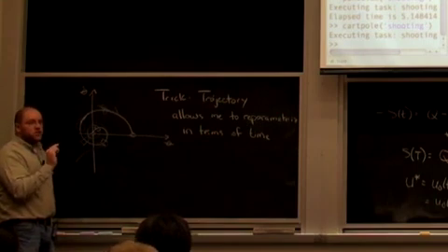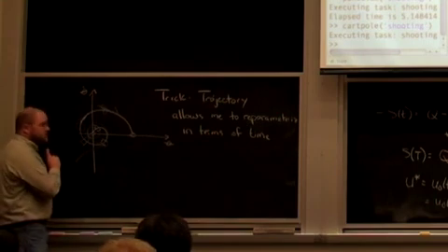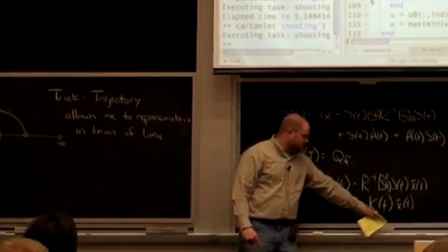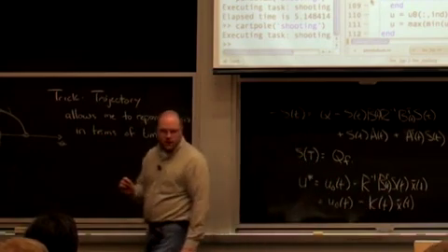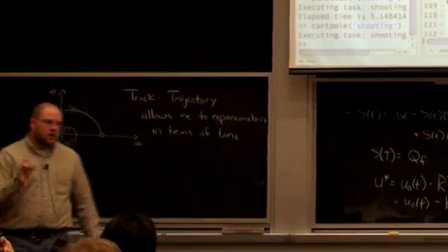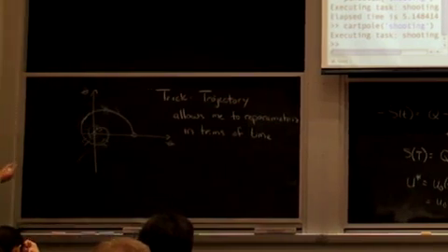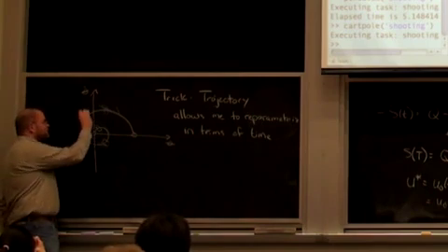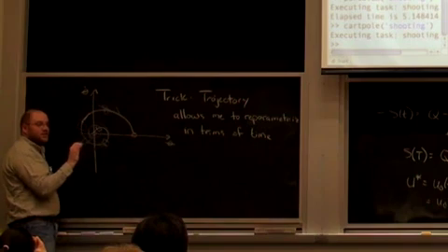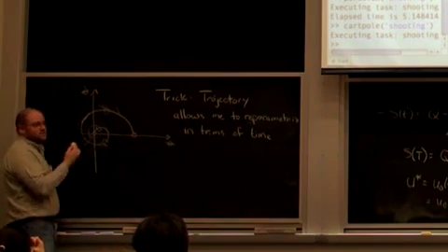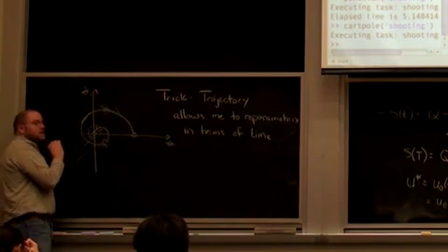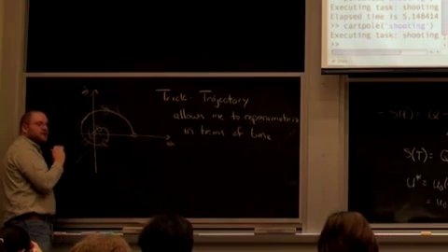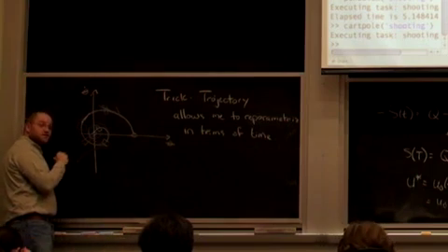You could think of this very much as a gain-scheduled linear controller. This is a time-varying gain scheduling, and the problem is if I switch gains quickly, then you're going to get chattering. So it might make a lot of sense, for instance, if you get a big disturbance, to reevaluate and try to find the closest point and start executing that new policy with time re-indexed. But in my experience it's probably a bad idea to decide which part of the trajectory you're closest to on every dt.